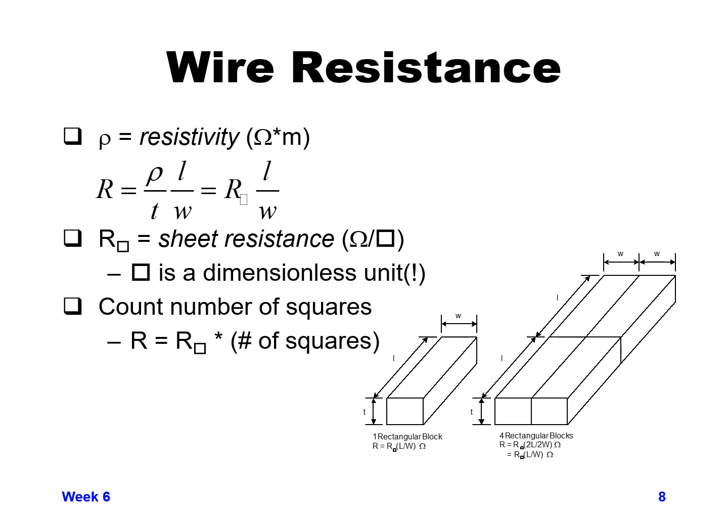It's just a function of the total L divided by the total W for a given wire that you've drawn out. So you can basically get the resistance of a given drawn wire by taking your ohms per square, which is a function of a particular metal layer in a particular process technology, times the number of squares, which is length divided by width.